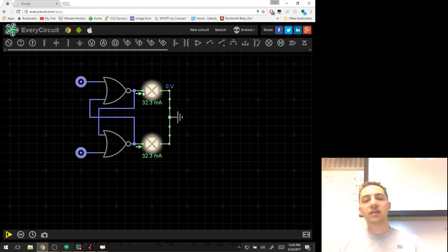We're seeing that this sort of brightness is an indicator that it is what we call astable. A meaning not stable. It's just going to keep flickering like a crazy person, okay, forever. Now, if we let this simulation run for long enough, eventually what's going to happen is because of differences basically down at the silicon level, differences in propagation delay, eventually one of these will get ahead of the other.